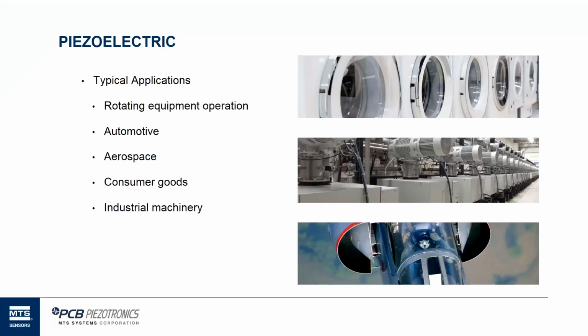We do monitoring and we do test. And when you're talking monitoring, we're usually talking about things that rotate, mechanical rotations, and things that go out of balance and need to be rebalanced, and monitoring these rolling elements in machinery to make sure the bearings are healthy and predict when the bearings are going to go bad.